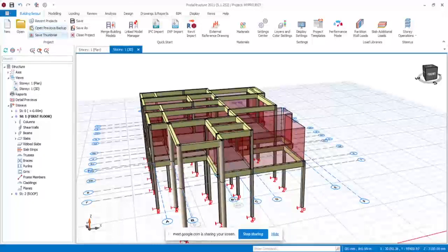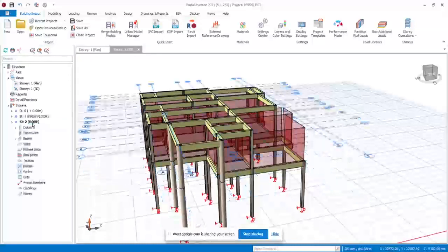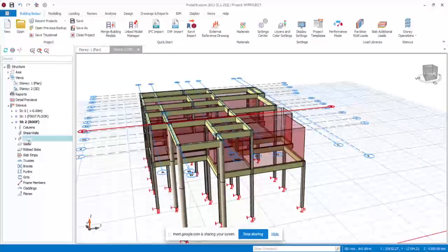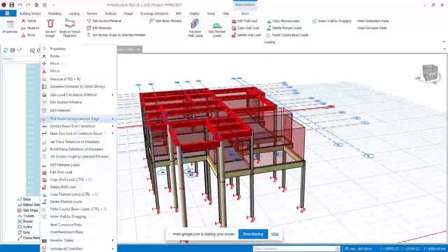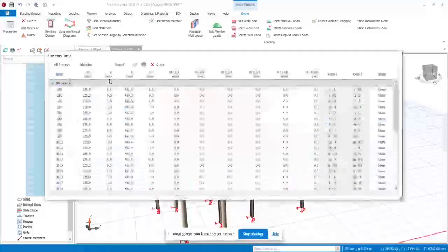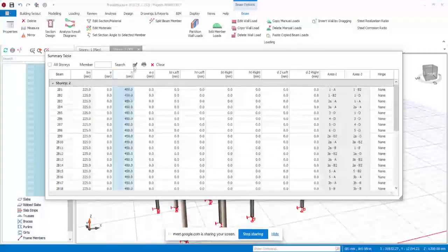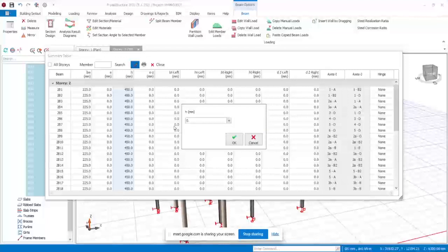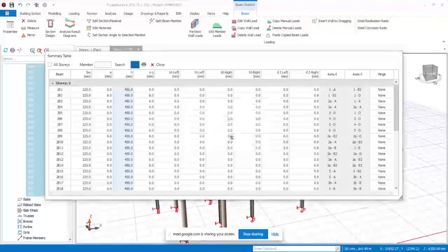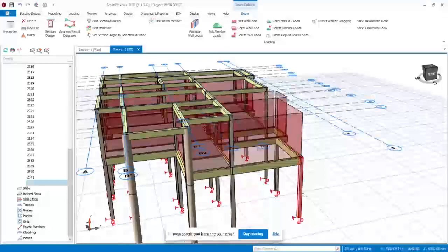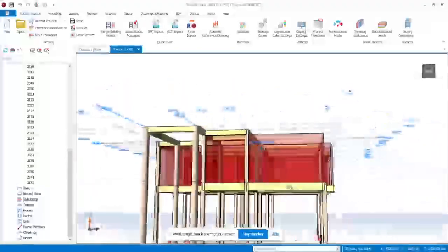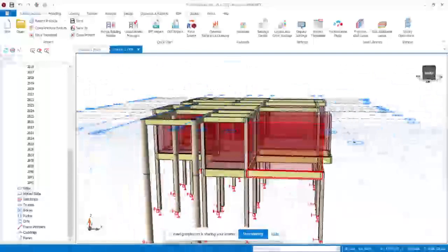All right. So I want to lessen the roof beams, the sizes to 300. So instead of doing one after another, I can come here, right click, properties, then when you find 450, you can edit them to be 300. So automatically everything changes to 300 beam. All right. So we're done with that.